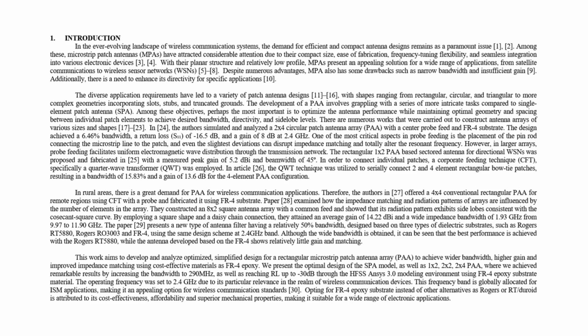In our design, we choose the edge feed with a corporate network due to its simplicity, ease of integration, and scalability. This study focuses on creating and evaluating an optimized, simplified design for a rectangular microstrip patch antenna array to enhance bandwidth and gain and to achieve an ideal impedance matching using the cost-effective FR4 epoxy material.